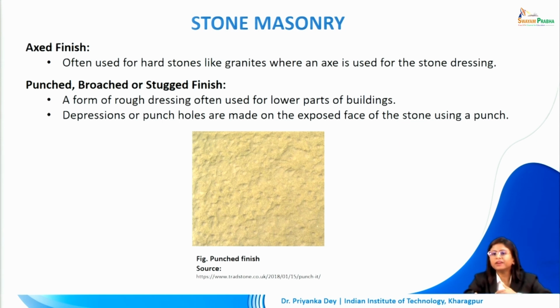So it becomes very clear that if we are going for stone masonry, we will have to dress the stone before we can use it for our construction. This is where brick masonry becomes more preferable in most regions, except for when bricks are not easily available, or stones are more easily available or are cheaper and can be used in construction. That's because bricks can be used without dressing. They can be used as they arrive on site. Whereas in case of stone, a lot of finishing has to be done before we can go ahead with the laying of masonry courses.